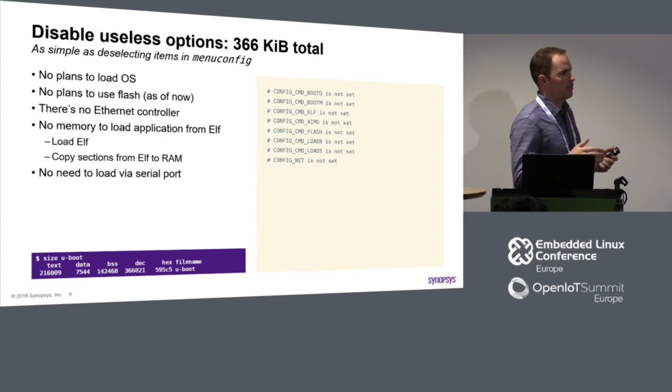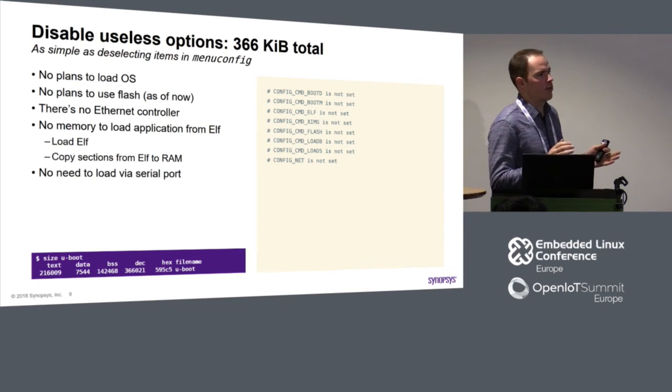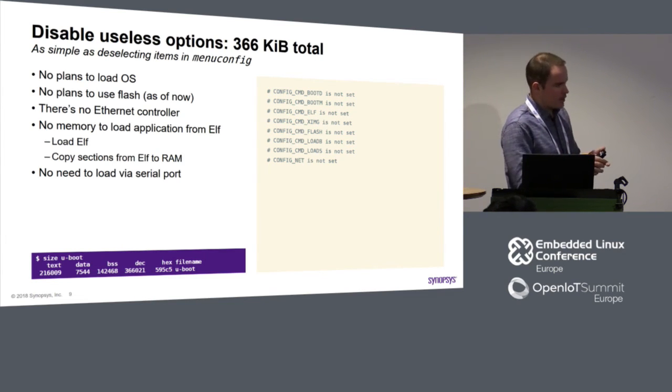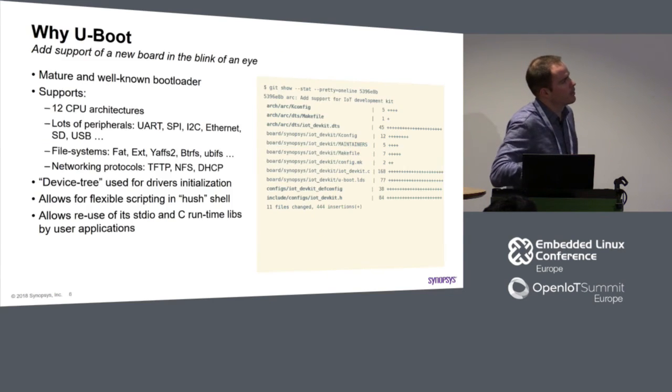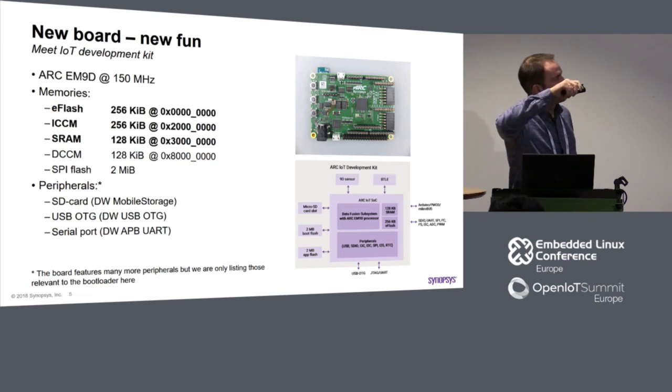The point is you build your bare metal application, which does, I don't know, sensor fusion, whatever. And it is 100K in size, I mean the entire binary. You may produce with a compiler not only an ELF file or a uImage, you may build a binary image of your application. Then you load it into memory, say here, your application, and execute it and do whatever you want.